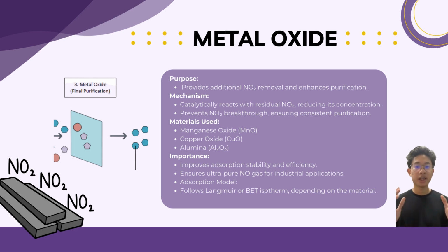The final purification layer consists of metal oxides such as manganese oxide, copper oxide, or alumina, which provide additional NO2 removal. These oxides catalytically react with the NO2, further reducing its concentration in the gas stream. These enhance the stability of the adsorption process and ensure consistent purification.